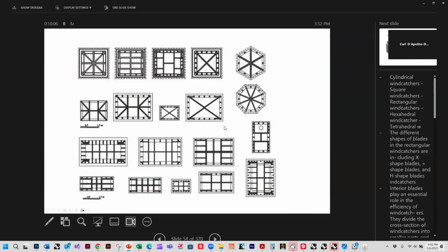So they're divided on the inside. They're divided usually with many little divisions, which are just kind of aesthetic, and then major divisions. The major divisions are there because there's usually an inlet and an outlet. The wind blows in here, goes down, and then there's an outlet for the air that's going out. So whatever direction is facing the wind, the air goes in, and then air comes out the other side, and that turns over the air in the building.